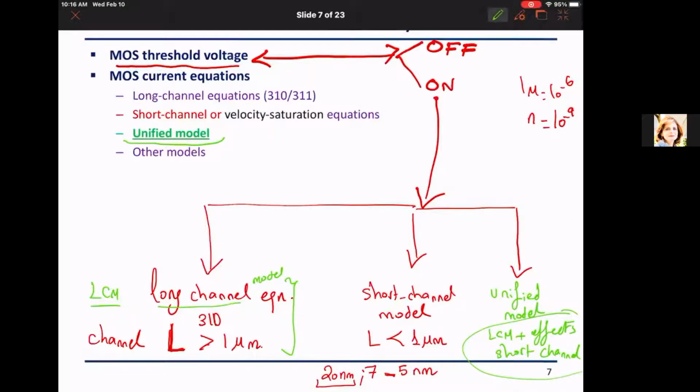Okay, so it will combine the two depending whether the short channel kicks in or not. We can then work out the analysis. So it will be similar to the equations that you have seen before with one extra conditional. Before, we used to check if VDS is greater than VOV. Now we're going to have VDS greater than VOV plus an extra condition. Okay, so don't worry about this, but I'm just trying to put the forward plan that is ahead of us. And of course, we will go over one example of another model.